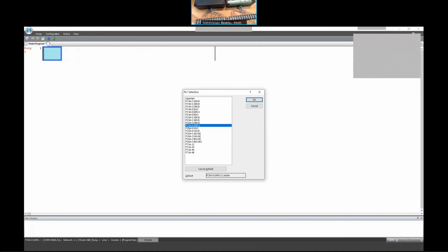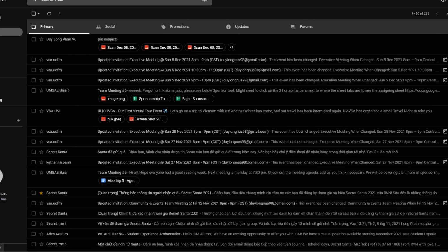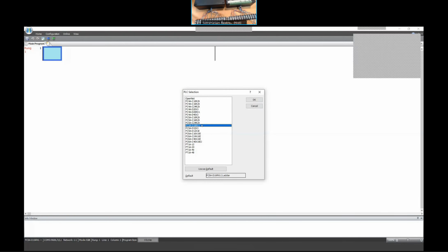If you set 24 and accept it and write the ladder logic program, when you want to actually download to the PLC, it's going to come back and not warn you. You will say incompatible PLC, that your program was written for something else, but easy to fix. You can go back and put the 16 back and let it recompile. Not a big loss, but be aware. This is written in my manual. Before you start, you have to set this up. Okay, so it's done.